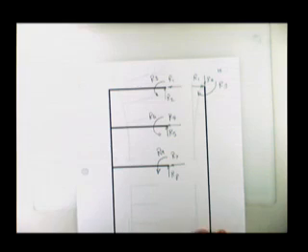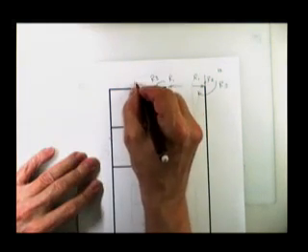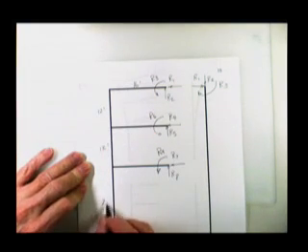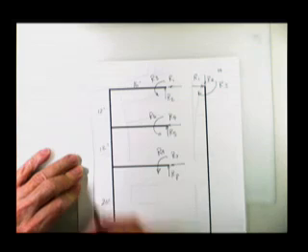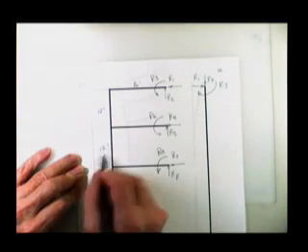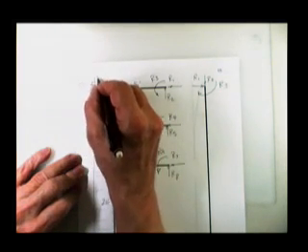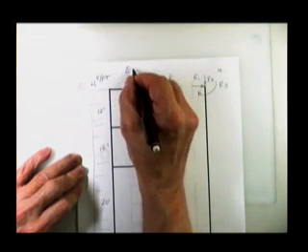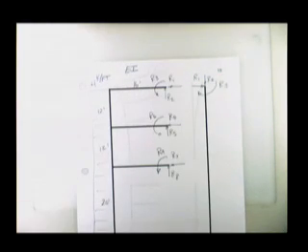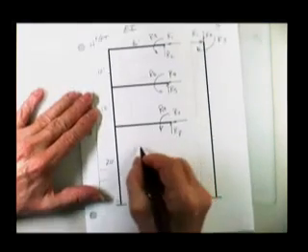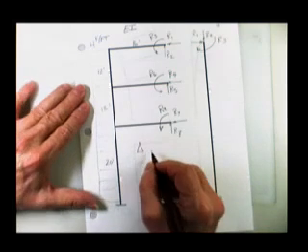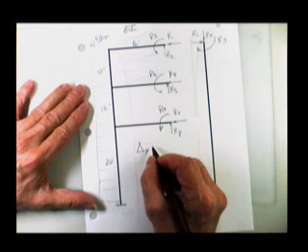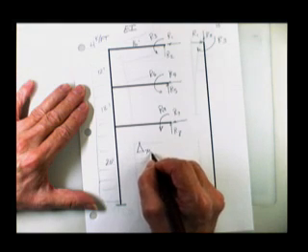And I want you to give me, this is again 16 feet, 12 feet, 12 feet, 20 feet. And there was a uniform load across the right-hand side of 4 kips per foot. The entire frame has a flexural rigidity of EI. And I want you to tell me the following number, the deflection in the number 7 direction due to the real loads.